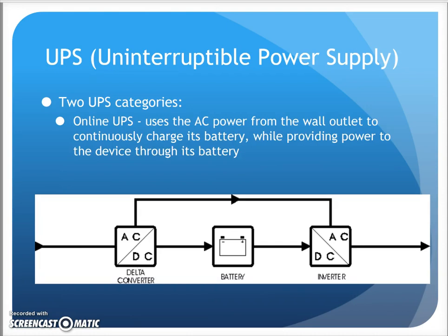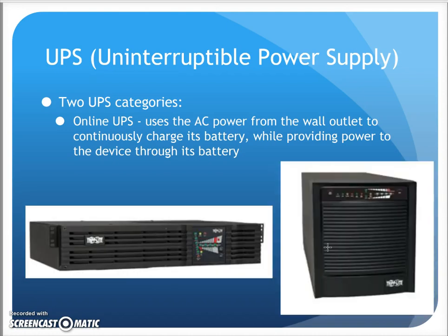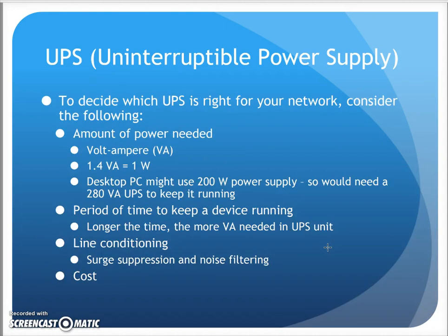Meanwhile, with your online UPS, your power coming in from the wall is continually charging the battery, and the battery is pretty much continually providing power to whatever's connected to it. Almost like your laptop, if you will. The laptop battery is always powering the laptop. When you plug it in, you're basically charging the battery. When you unplug it, you're no longer charging the battery. That's the concept of your online. And your online UPSs are usually the better unit because it's providing nice clean power all the time, and the only problem is when the power goes out, it's no longer charging. So it's like, okay, I'll provide power until we can plug it back in and start charging again.